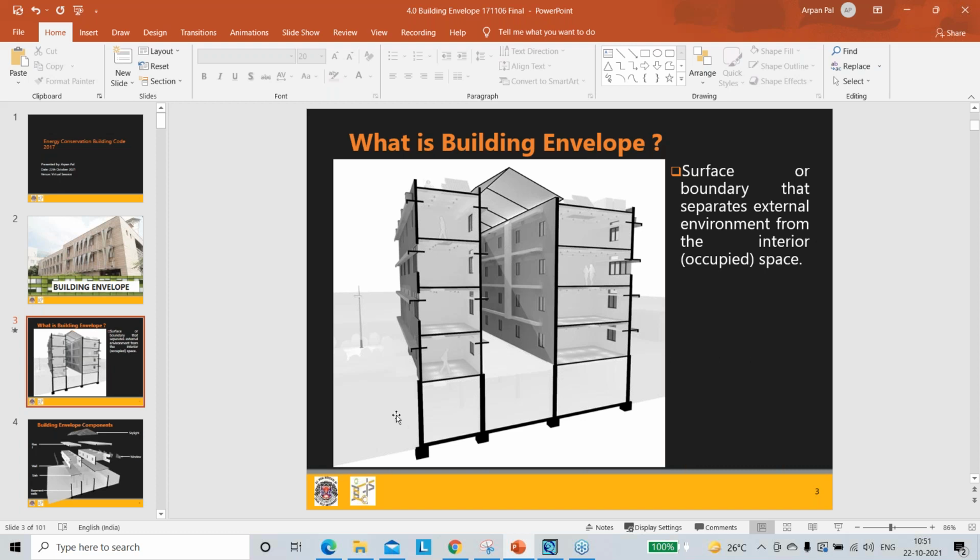Interior ceiling, floor, and internal partitions do not influence the energy consumption of your building that much. It is the other aspects: the skylight, the fenestration, the roof, and the external wall. In fact, the underground wall as well. If there is a basement, that is also influential.